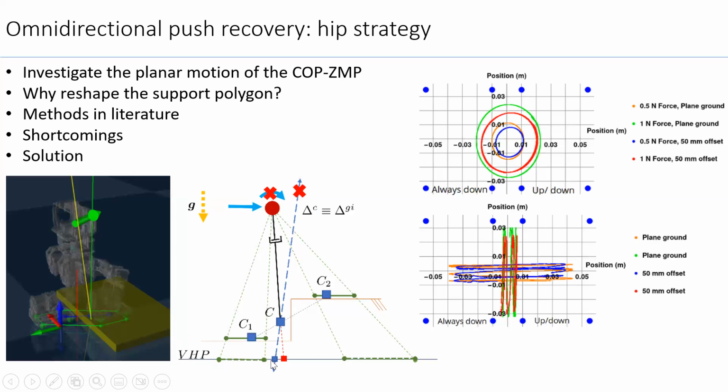So this plane, if we take it up higher somewhere, then it may happen that the ZMP lies outside the support polygon. So what we have suggested, that is the solution, is that we take a point on the ZMP axis and then project with it as focus. Now this work is supposed to be published in an upcoming journal, and it's novel.